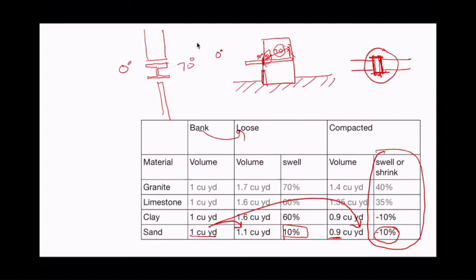That piece of steel is going to be cold all the time, just going from outside to inside. So instead of using a wide flange in that scenario, with our wall above and our door below, we can use 2 C channels and a piece of wood in between, because wood is not nearly as conductive as steel.